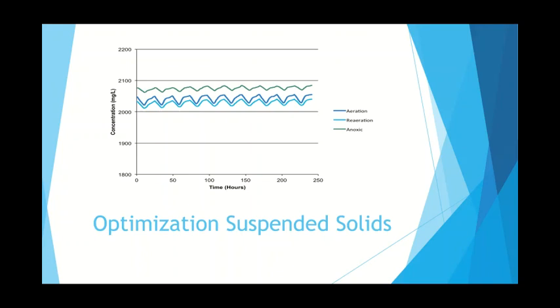Also, after optimization, the suspended solids concentration appears to remain much more constant than in the initial model. Further optimization could be done by adding a controller to maintain a higher level of suspended solids.